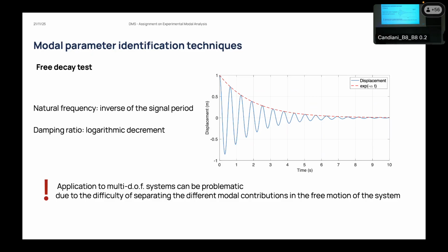We have a structure that we know has an infinite number of frequencies, but if we are close to one of the natural frequencies of the structure, we could approximate the response of the system with just one mode, that is the resonant one.